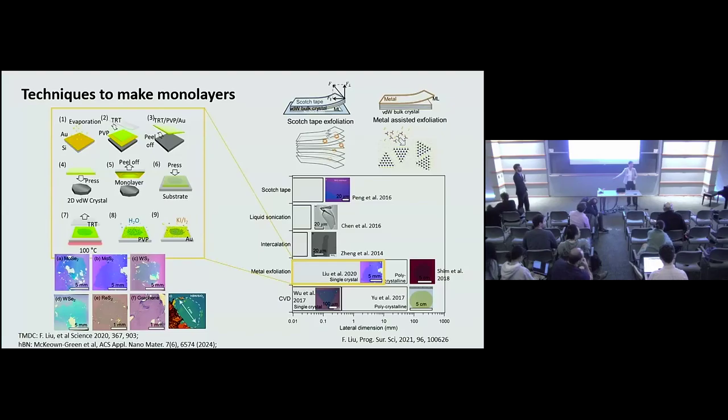Why can you not get thick layers? That actually comes from the exfoliation mechanism. The exfoliation mechanism is a spalling mechanism, where you initiate a crack, and that crack propagates along the crystal domain surface. You can estimate the crack depth from the HBN's mechanical parameters.